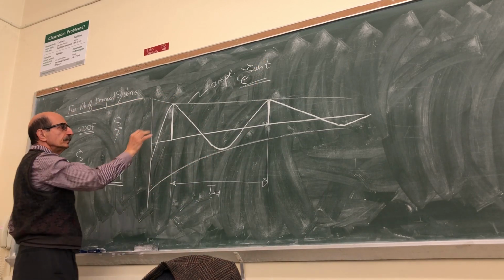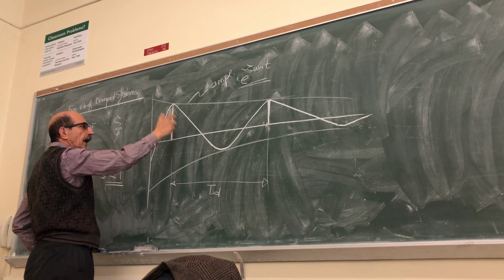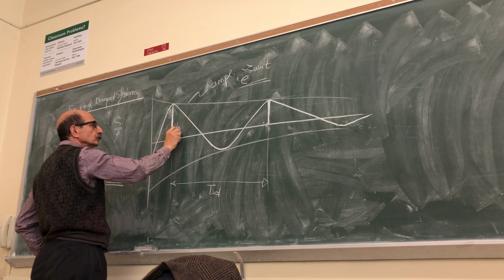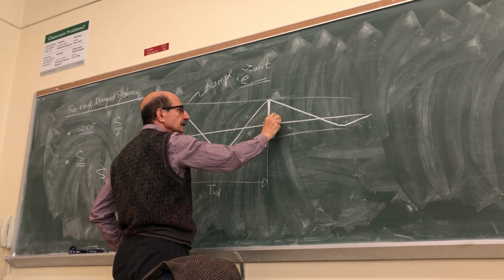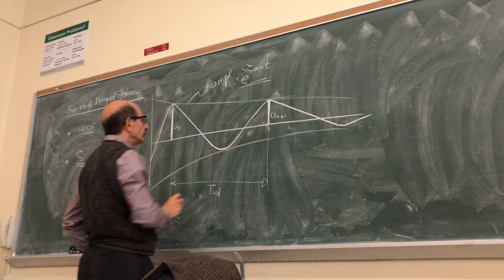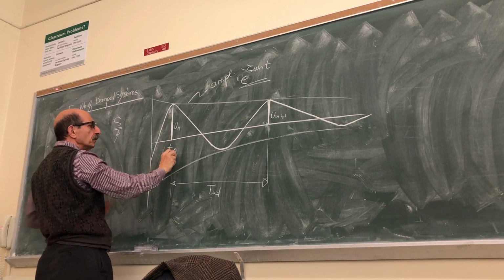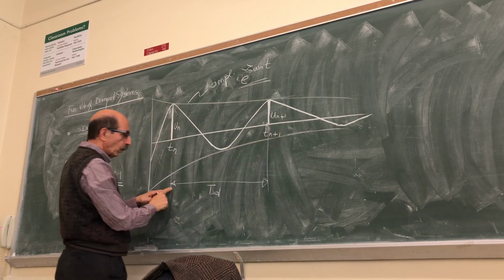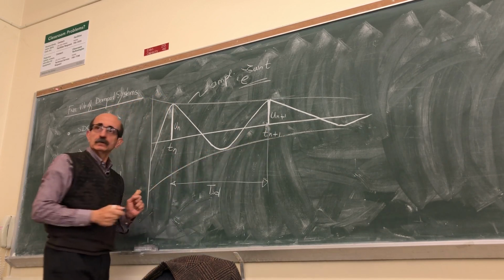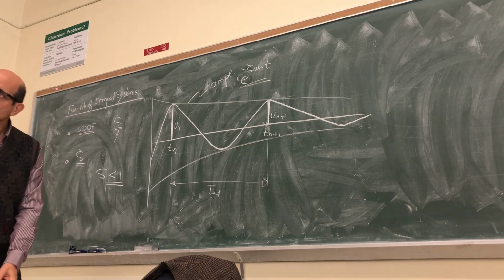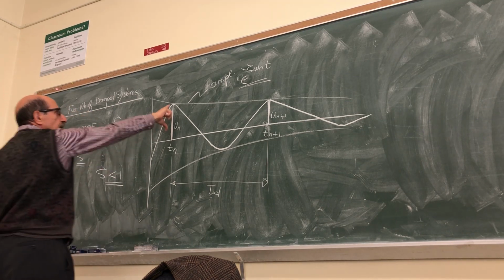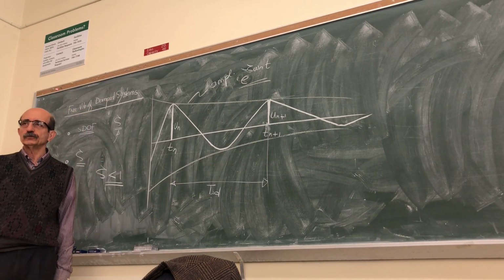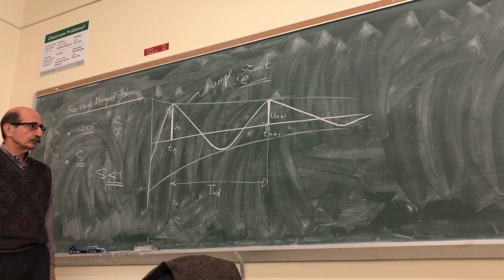Let's say you can measure the amplitude of two consecutive peaks, okay? I call this U sub n and U n plus 1. In other words, you measure this at some arbitrary time, and this is at a time one period after that. Okay? What we want to demonstrate is that as long as you can make these measurements, you can actually find the damping ratio in the system, or measure the damping ratio in the system.